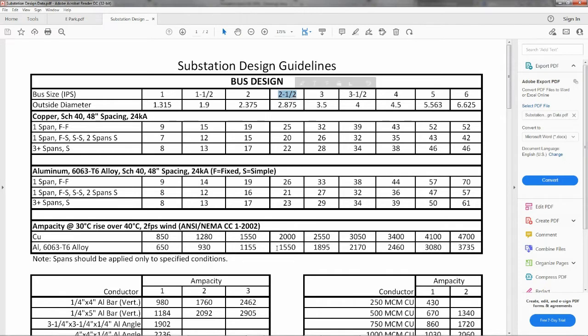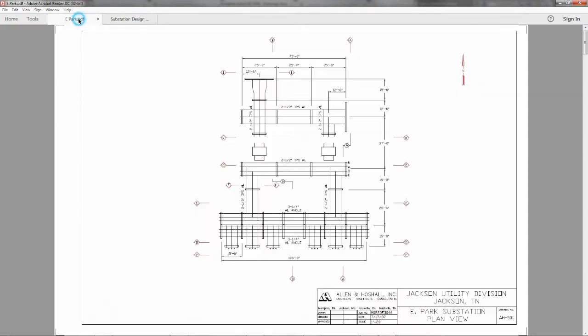On the 12 kV side, the ampacity of that is 1500, which is over 30 MVA. And since these are 15 MVA transformers, then that ampacity is certainly adequate for what we're doing. And generally, rather than doing a lot of different bus sizes, we will keep the same bus size throughout these main buses through here. So given that, let's go into our design.